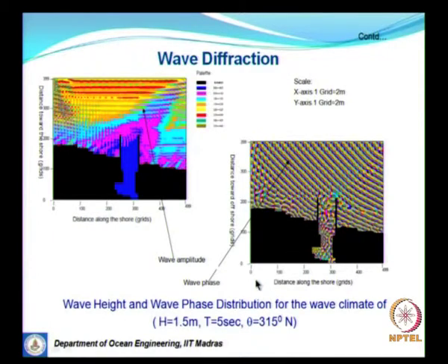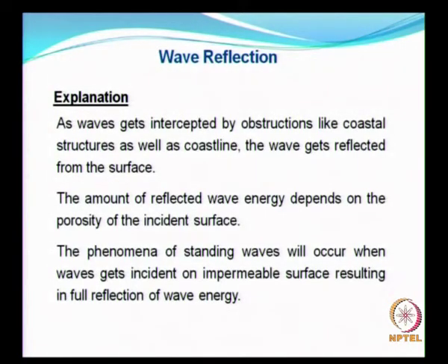So, earlier we saw normal wave angle of incidence. Now we have what is called phase contours, which show how the waves move. You see that the waves are bending, and once they enter a narrow area it becomes complicated because you have reflection from the side breakwaters, etc., and so you will have a different issue.